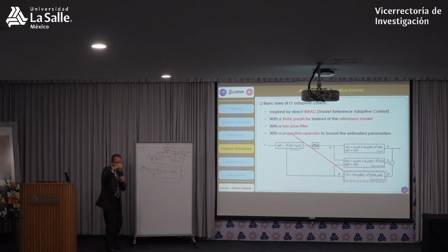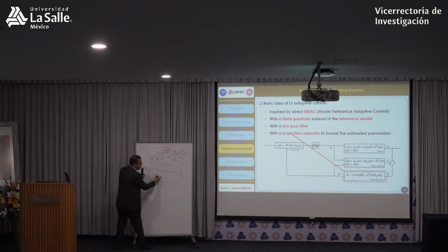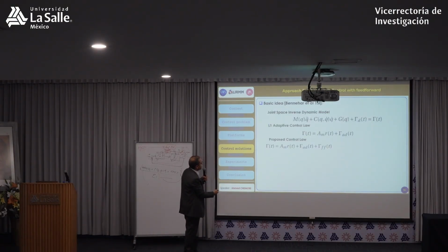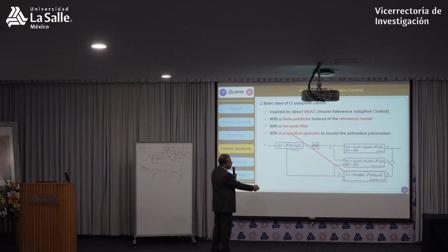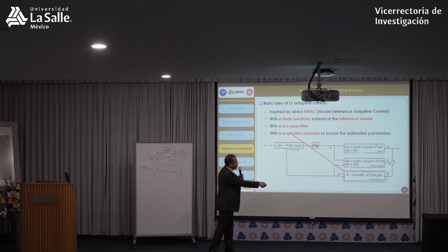You do a first nonlinear feedback to bring this model to this model. And once you have this model, the tau that you choose here, pay attention, is not based on the model. You will not use M and C and so on. It's a feedback that brings this nonlinear model to this. And this is why, if you look, here, AM corresponds to this linear model. So you have a first feedback that brings you from this nonlinear model to this linear model, and you construct your controller based on this linear model.